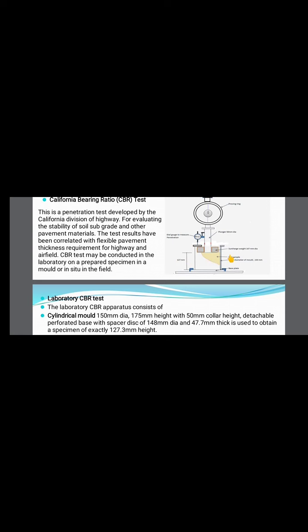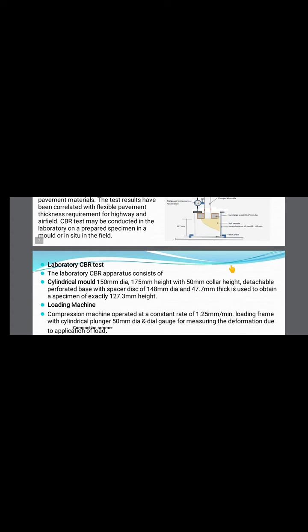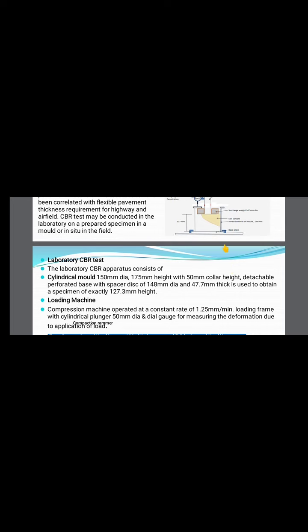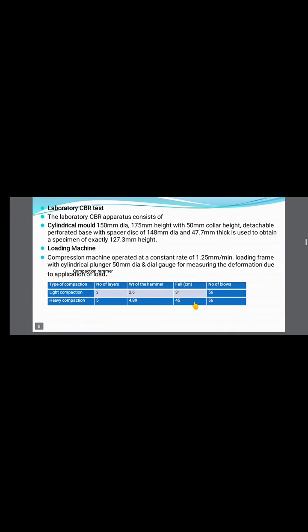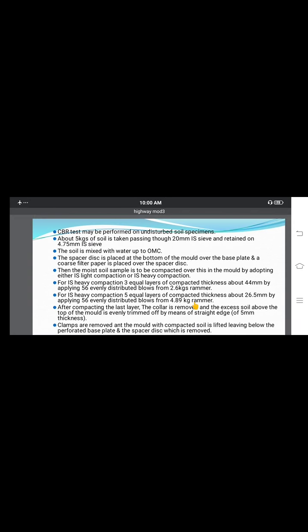Above that, a detachable spacer disc of 148 mm diameter and 47 mm thick, used to obtain a specimen exactly 127 mm in height.